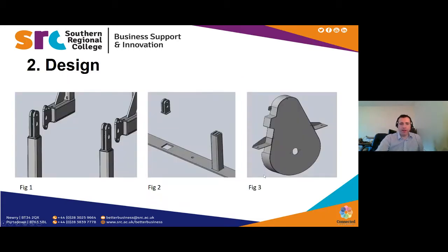I find anyway. If I take it to the next step here, I wanted to identify where DFM comes into its own. Figure 1 is showing very simple brackets. I call them lollipops, but they're brackets there. What I'm trying to show you here is that using standardized thicknesses of brackets, a standard design that can be repeated throughout the design and for other projects, standard nuts and bolts can be used to attach the parts together.